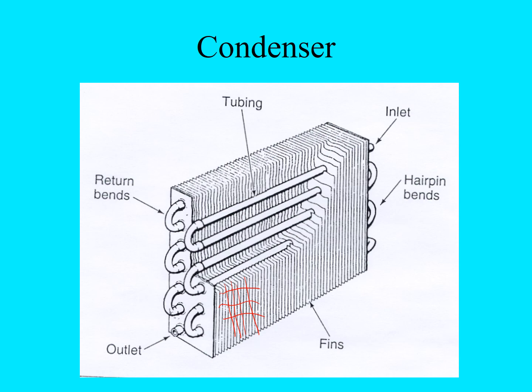And I've had some refrigeration systems that seem to not work properly, and you flush the condenser out with water from the back side just to blow the dirt out of it, or use compressed air to get the dirt out of it, and it will help get the condenser working properly again and the AC system. If we can't give up the heat in the condenser, then we can't extract the heat out of the interior of the vehicle at the evaporator. So the condenser has to work as well as the evaporator for the AC system to work properly.